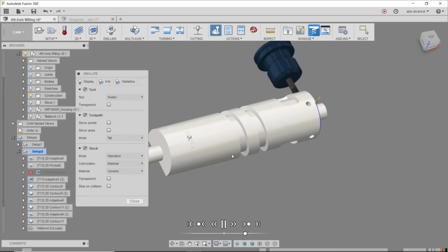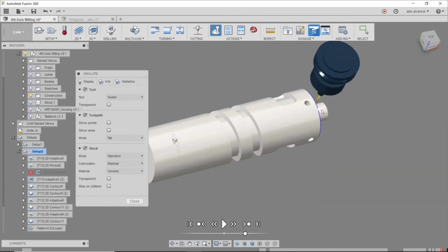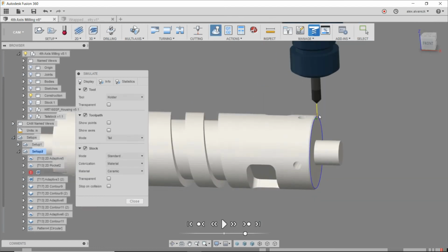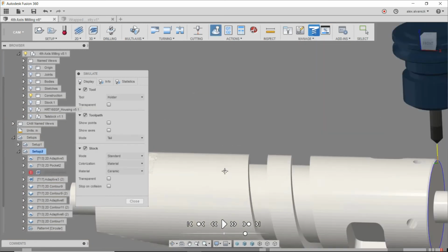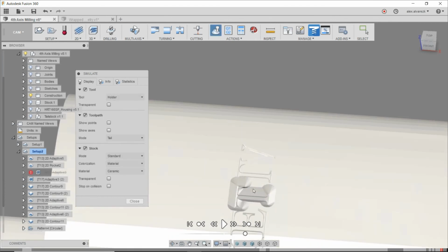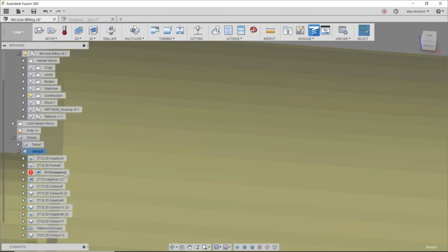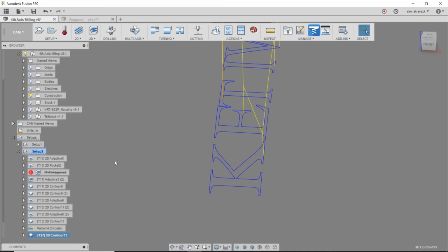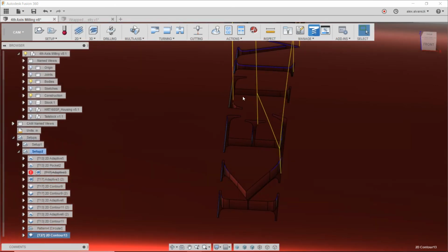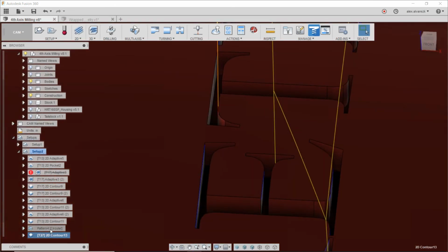So you've pretty much done almost all the tooling on this part. Yeah, pretty much. So here we see the chamfer. What you can do here is, again, use tangential extension and extend that toolpath a little bit further, right? So it looks like we got some error here on point. So yeah, it looks like it plunges into here. So what you can do then is just make sure that you go back into the tool and have the correct, yeah, okay, so looks like I selected the wrong geometry there.